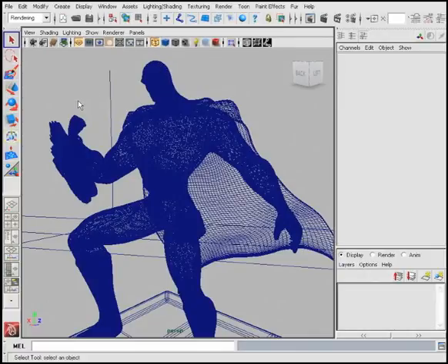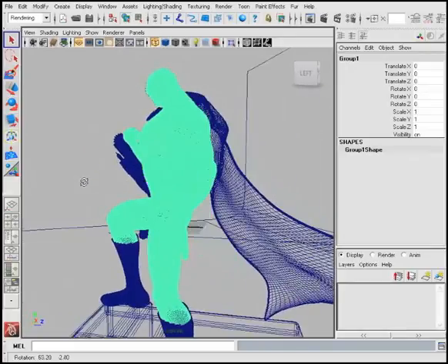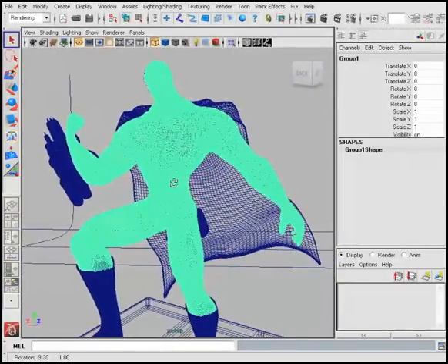and this is a feature called Render Proxies. Now basically what this feature will allow us to do is offload the geometry outside of our scene. So what we'll do is basically take a piece of geometry, export it, and then link that geometry to something very, very simple. So that way the high-res geometry is not visible here within the viewport. It will only be called in whenever the render takes place.